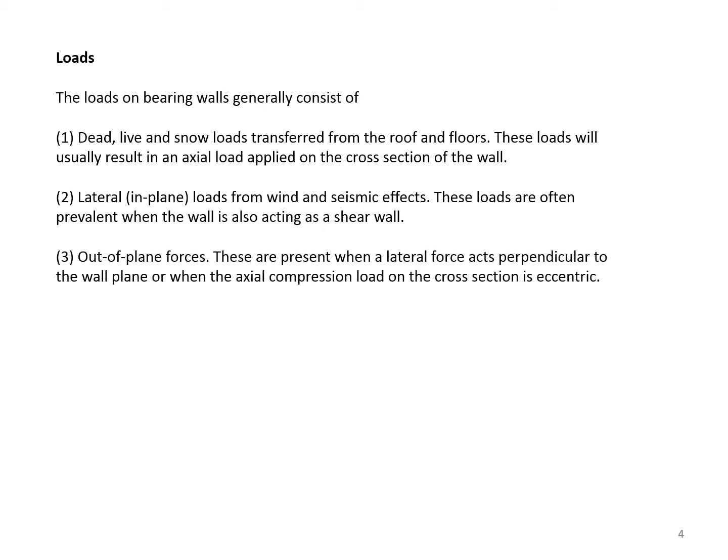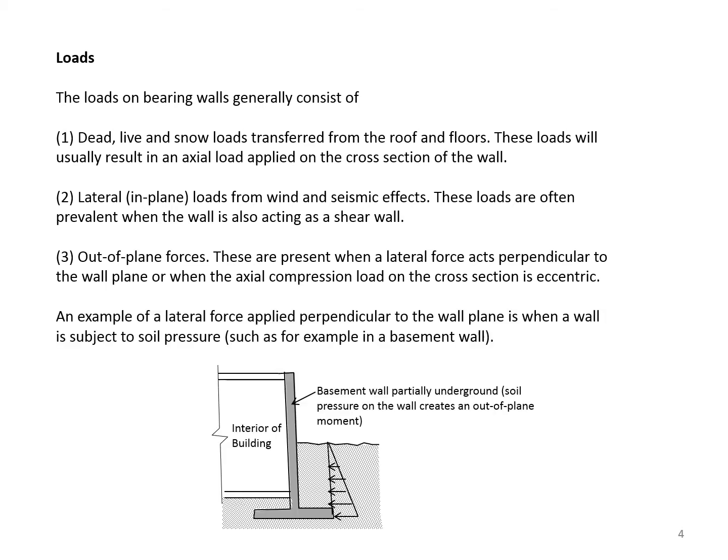And out-of-plane forces. These are present when a lateral force acts perpendicular to the wall plane or when the axial compression load on the cross-section is eccentric. An example of a lateral force applied perpendicular to the wall plane is when a wall is subject to soil pressure, such as for example in a basement wall as shown in this figure.